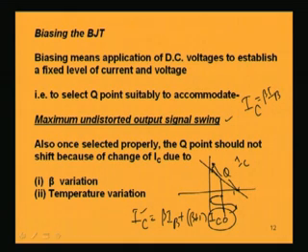IC will increase means again the Q point will be shifted. So, you may reach again near saturation, or vice versa. If temperature is decreased, you will have a decrease in IC because of the fall of IC naught, and the Q point will shift towards the cutoff region. And this should never happen once you select that Q point; that has to be ensured.